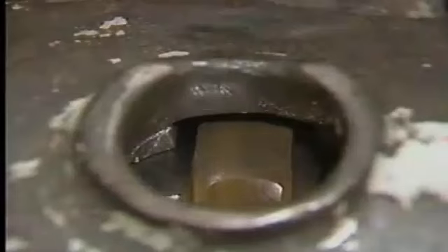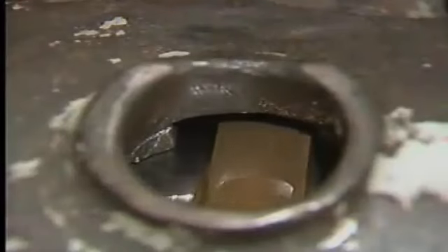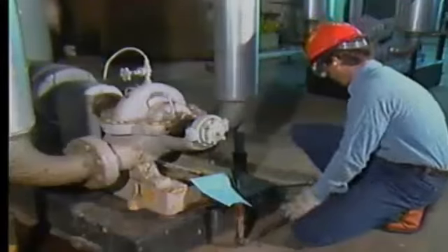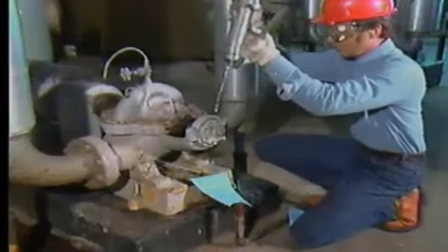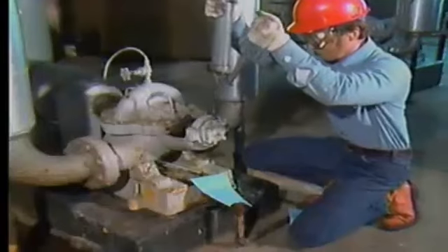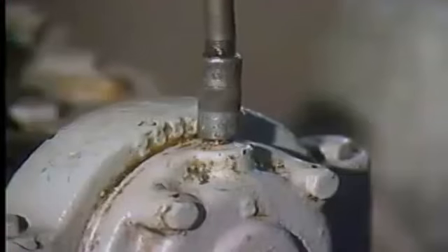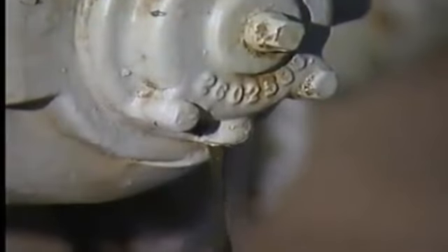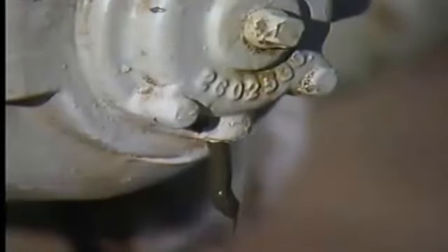Contaminants in the lubricant can also cause problems. A liquid contaminant, such as water, can alter the properties of the lubricant and adversely affect the lubrication process. Solid contaminants, dirt for instance, get pressed between the bearing and the shaft, where they can cause damage to both parts. Using the wrong kind of lubricant also affects the creation of the film of lubricant between the bearing and the shaft. The lubricant in a particular sliding surface bearing must have the right properties for that bearing.